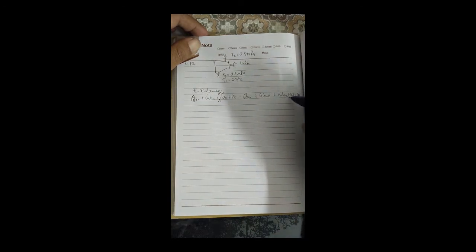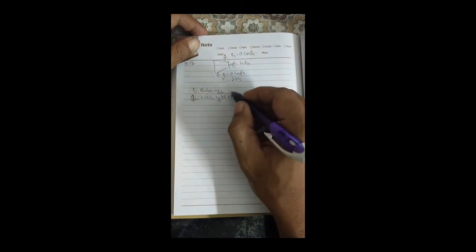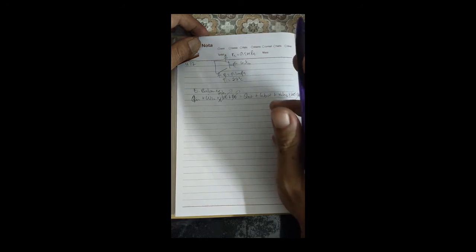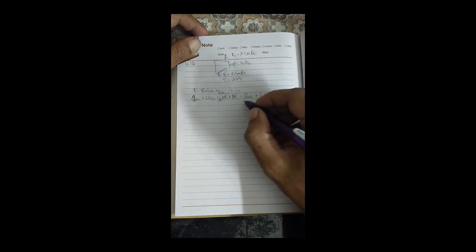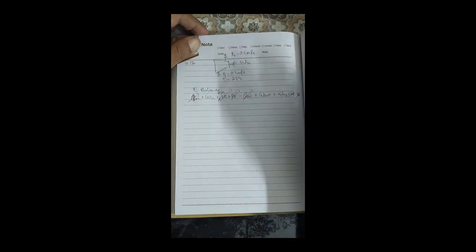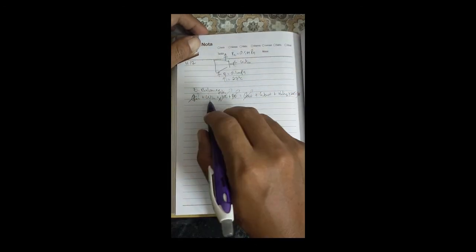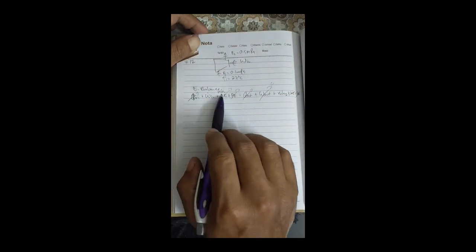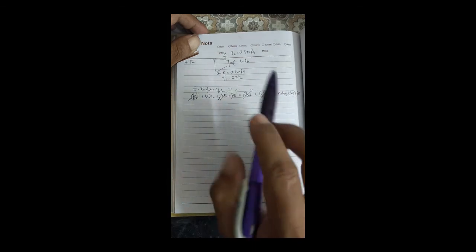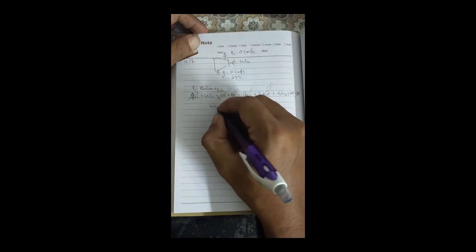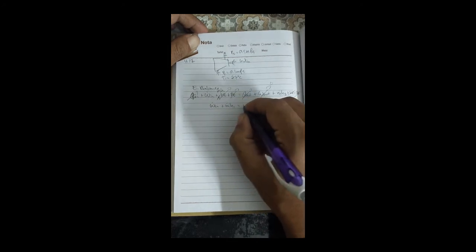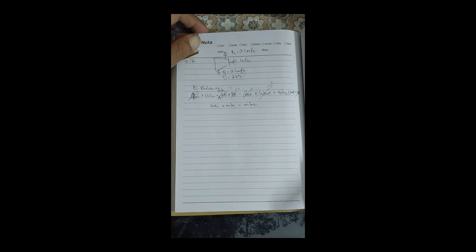We take out the kinetic and potential because we assume they are negligible, and it's adiabatic. Adiabatic compression is stated in the question, so no heat transfer. As a compressor requires work in, work out is negligible. So left is work in plus m dot H1 is equal to m dot H2.